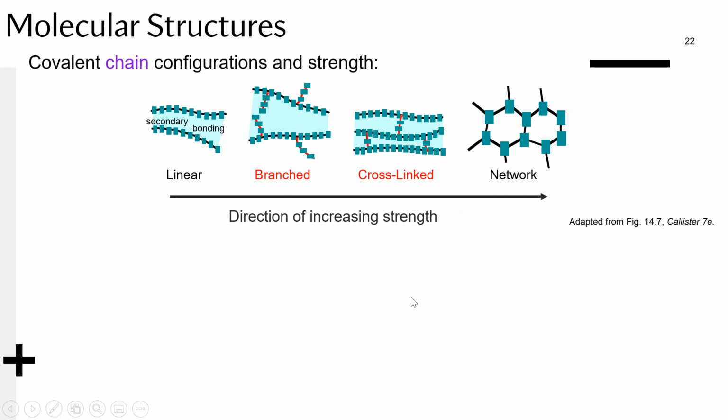So what you see here is that you've got a cross-linked set of chains that have actually got lateral bonds that are also covalent bonds, as well as the covalent bonds that connect the main backbone of this structure. So if this is organized to a degree that you can see some sort of repeatability, it's more of a network structure or a crystalline structure, as we will see in a minute.